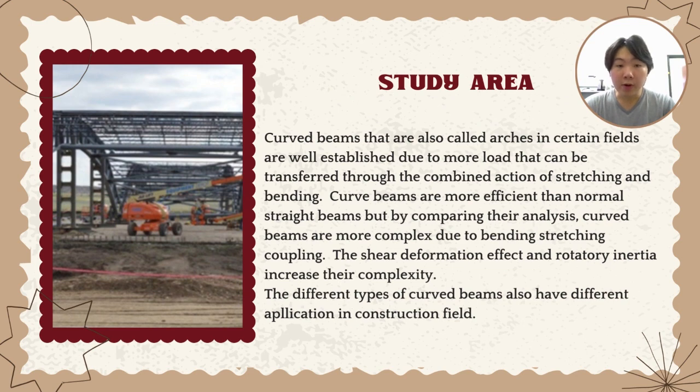Curved beams, also called arcs in certain fields, are well established due to the more load that can be transferred through the combined action of stretching and bending. Curved beams are more efficient than normal straight beams, but by comparing their analysis, curved beams are more complex due to bending-stretching coupling. The stress deformation effect and rotatory inertia increase their complexity. The different types of curved beam also have different applications in the construction field, which will be introduced in the later part.